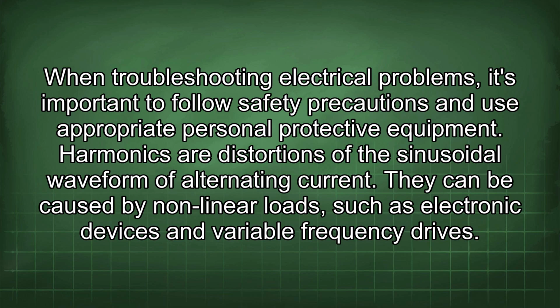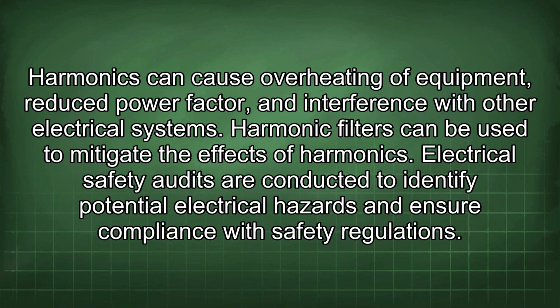Harmonics are distortions of the sinusoidal waveform of alternating current. They can be caused by nonlinear loads such as electronic devices and variable frequency drives. Harmonics can cause overheating of equipment, reduced power factor, and interference with other electrical systems. Harmonic filters can be used to mitigate the effects of harmonics.